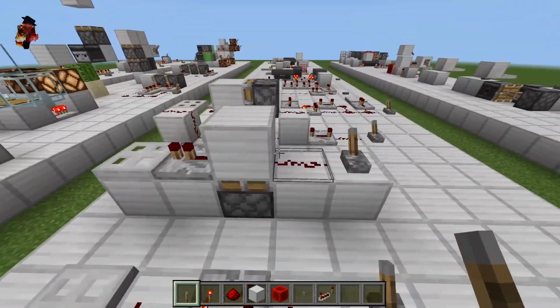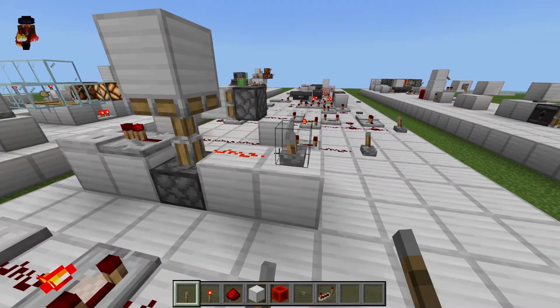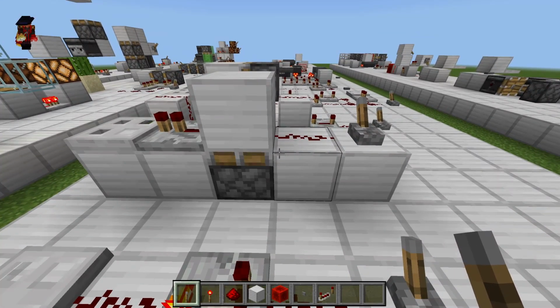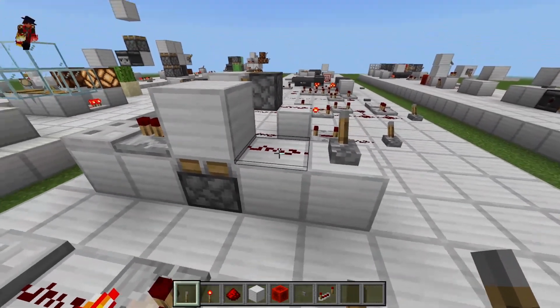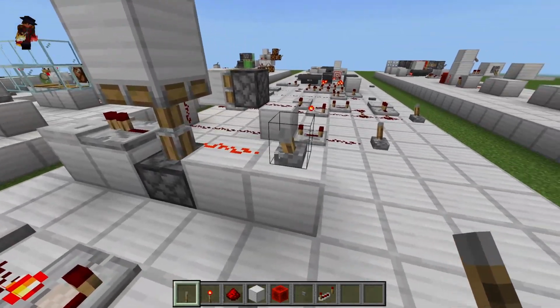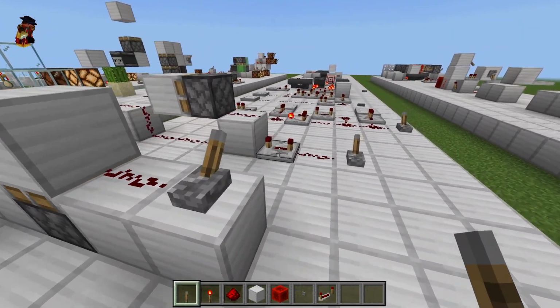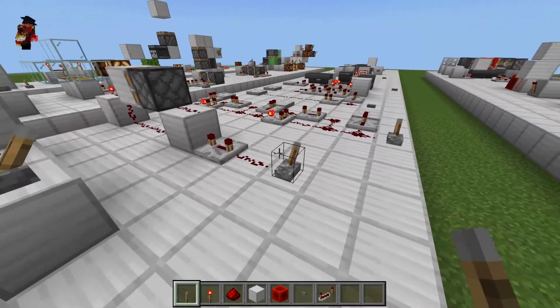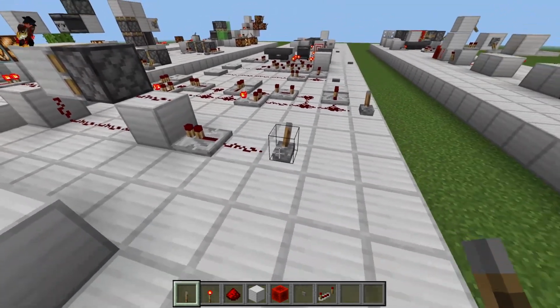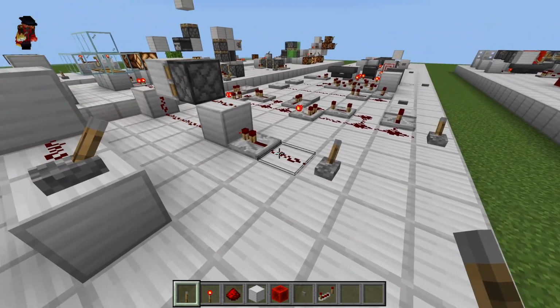Here we also have a monostable circuit, which basically shortens a pulse, which also acts as a pulse generator if you put anything in there. So here we have an infinite pulse coming in and a 1 tick pulse coming out. And here's a similar thing, but this time it's a 4 tick pulse, and that's a 1 tick pulse.